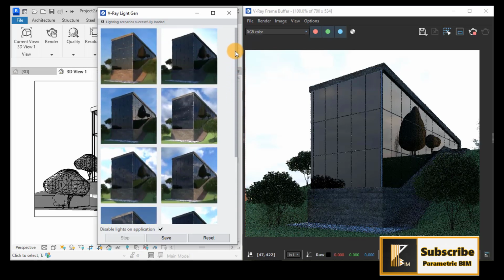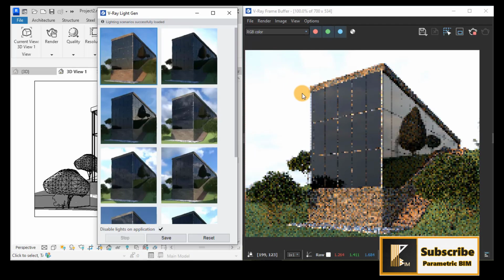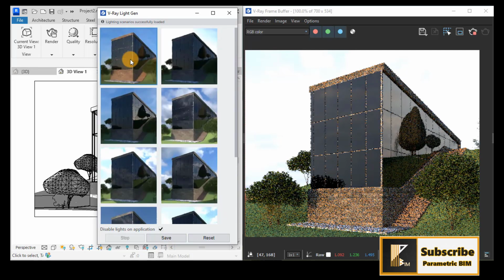So if I double click here, for example, you can see now that the interactive mode will adopt this lighting type, which is the azimuth and altitude at a certain point in the sky, and you can choose from them what is suitable for you, and then you can also save this to be used in the next rendering.